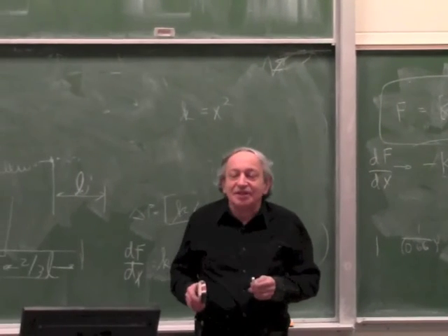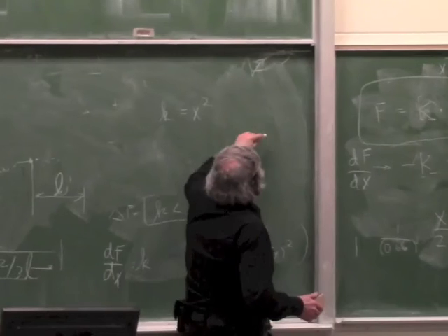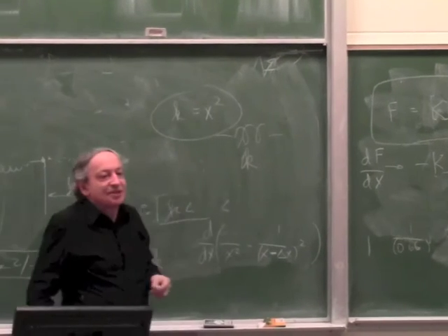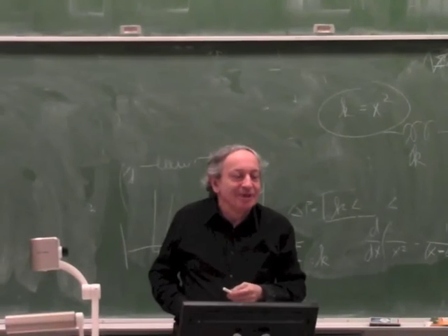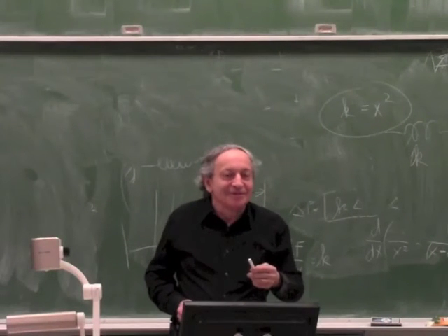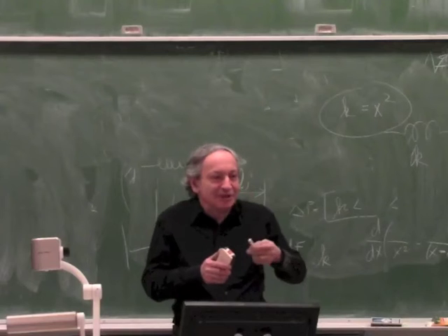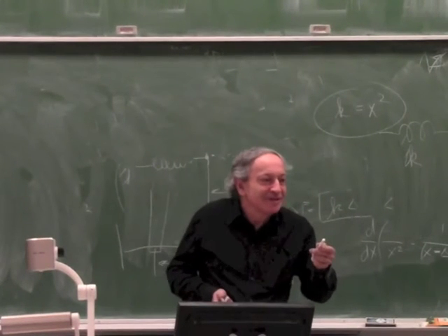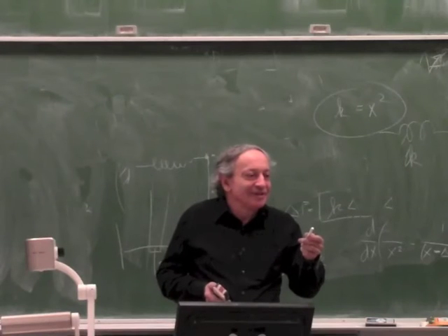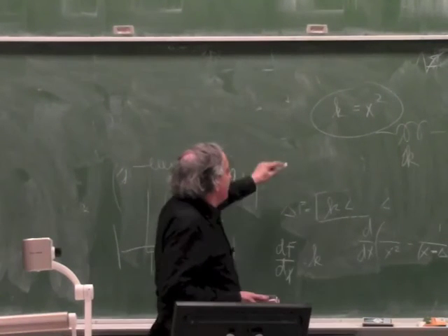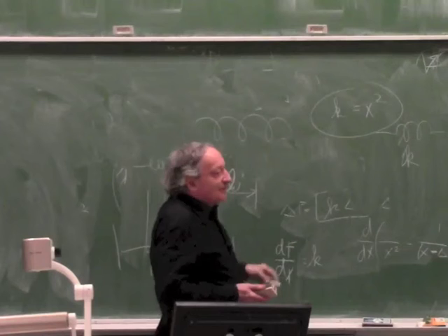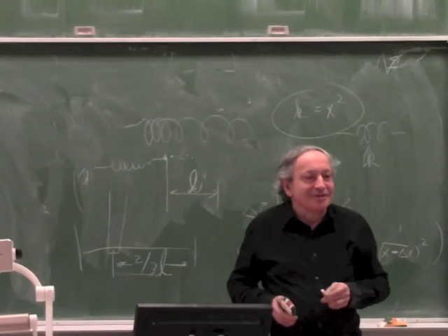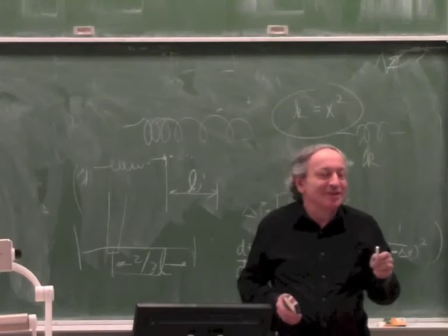Now, can somebody think how you make a nonlinear spring? If you take a normal spring, it's a constant k. How do you make a spring where k is not constant but x squared? Varying thickness or diameter? Varying thickness is difficult, physically. You could vary the pitch of the helix, and then what will happen? If you just vary the pitch of the helix, it's still linear. There's no effect on k. There are a few simple tricks to make a nonlinear spring.